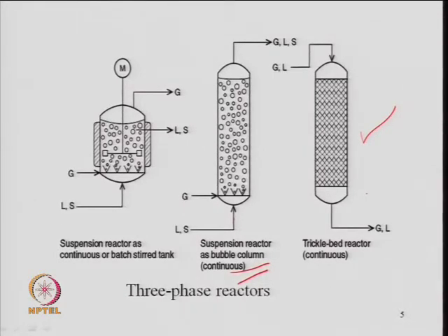So, we need a good kind of contact between gas, liquid and solid. We need a definite kind of wettability, because wetting and wettability both are very important in these kind of multi-phase reactors, right. So, dead zones may come because of inefficient catalyst or inefficient wetting during the reaction. Depending upon the flow rate of gas and liquid, the flow or hydrodynamics may be affected, and because of that the pressure drop may be an issue.